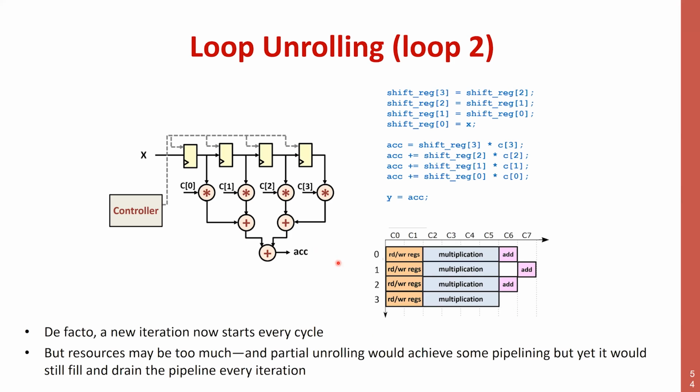But once more, this is pretty efficient in terms of timing, but potentially not the best that I would like to have from a perspective of hardware, because it's relatively expensive. Imagine if I have a 256 taps filter, I need 256 multipliers to achieve this kind of performance.